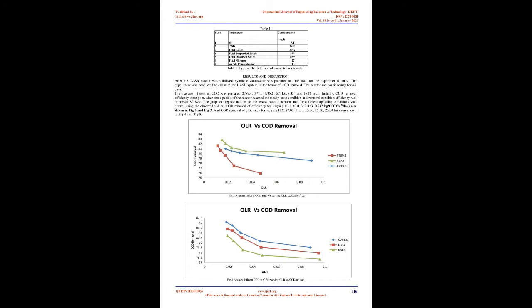Initial reduction with the increased OLR was moderate, and it tends to increase with the decrease in OLR. The effect of varying HRT was investigated. Removal efficiency was optimum at the high retention time. The decrease in efficiency when reducing the HRT, despite increasing the turbulence of the reactor, is because the contact time of the wastewater with the sludge granules decreases, so less organic matter was utilized.